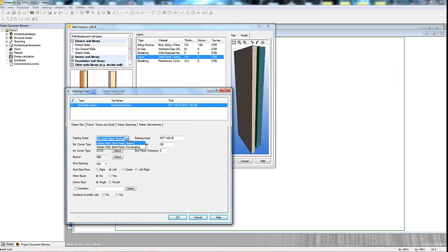Framing details determine if the wall is load-bearing or not and adjust the joints as per the system parameters. Panel label is the prefix used when the user generates the panel breaks. This will automatically pick up the level the user is adding the wall into. End panel tolerance enables the user to shorten panels to create a gap at panel breaks. Insulation can be added within the frame using the checkbox.